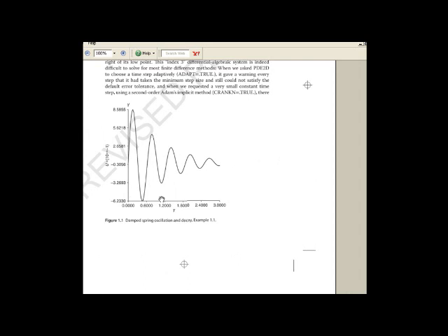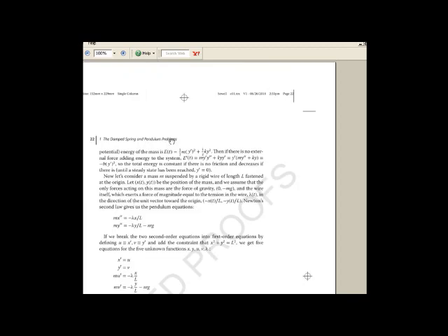And here's the same plot that I just showed you, except that you can see all of it now. And the spring is vibrating up and down and gradually dying down because of the friction, the B term. And an interesting fact here is that the energy of that system, assuming there's no external forces, is the kinetic energy, which is 1/2 mv squared, plus the potential energy, which is 1/2 ky squared.